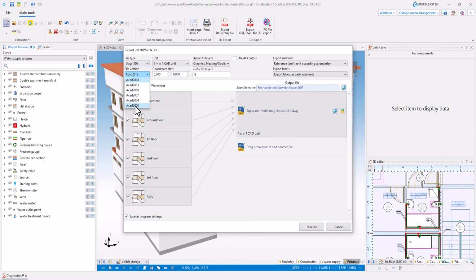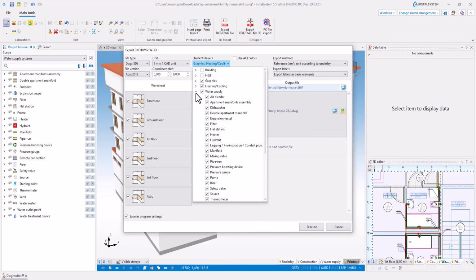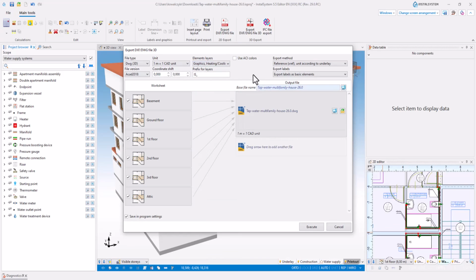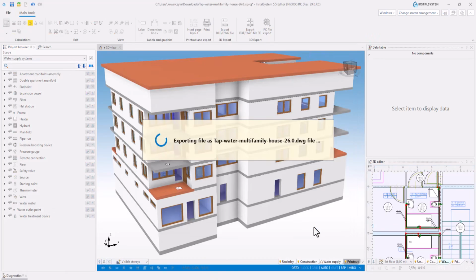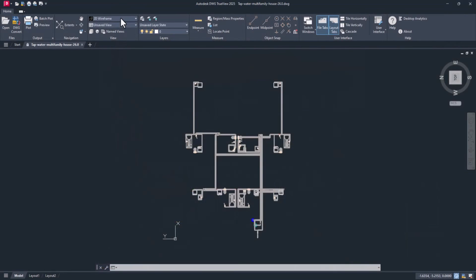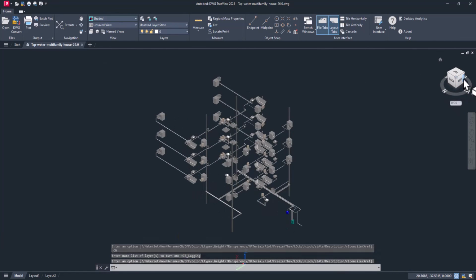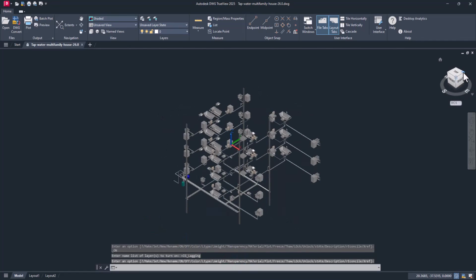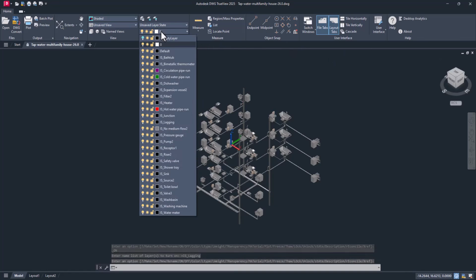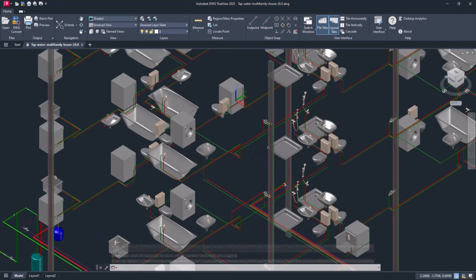The export window offers a set of options similar to classic DXF DWG export. This function extends the existing 2D export capabilities, allowing you to conveniently transfer your 3D model to other design applications and CAD viewers. Access to this function depends on having the appropriate BIM IFC export modules configured. After exporting, the 3D file can be opened in an external program, such as Autodesk TrueView, to verify its contents. The new feature significantly facilitates the exchange of data between programs and allows for the quick creation of 3D visualizations of projects supported in external CAD environments.